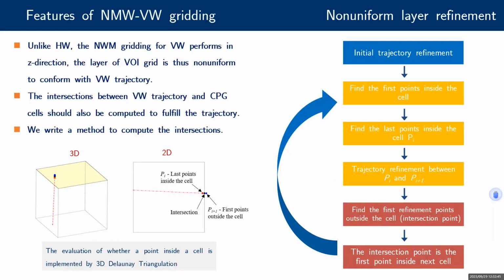The well trajectory is constructed from a series of discrete well points entered by the user, which may represent important features such as packers, downhole tools, and interlayering, etc. Therefore, each subdivision layer of the vertical well grid must correspond to each well section. A layer may contain multiple uniform well sections.